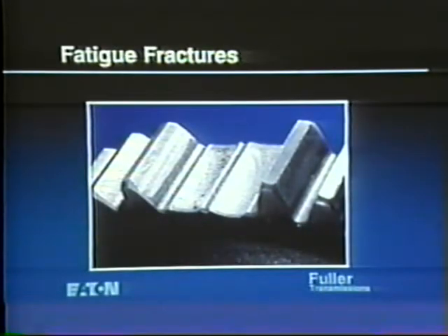Fatigue fractures are identified by beach marks on the fractured area. These marks are made as the tooth progressively cracks under a load that is heavy enough to enlarge the crack, but not great enough to break the entire tooth off at one time.